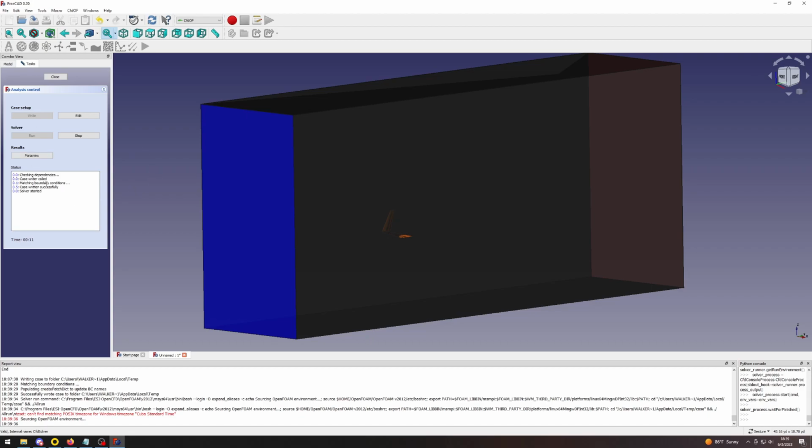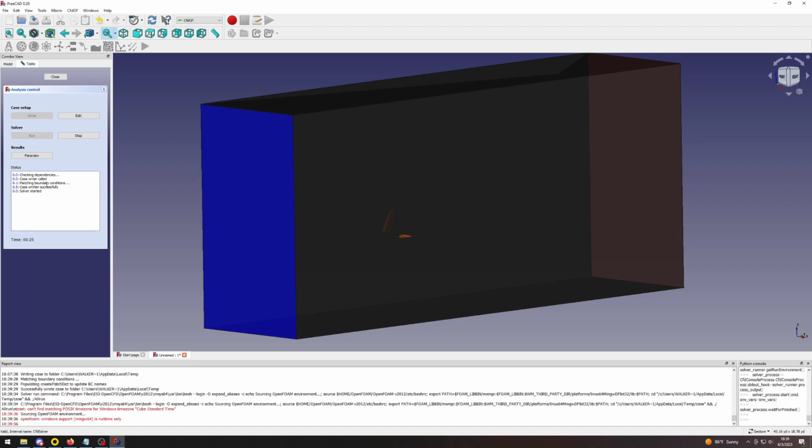And that second viewing of ParaView, where we open that program, is where we can really start calculating lift and drag as well as visualizing airflow, and there's a few different ways we can do that that are pretty cool. So I'll walk you through that when this is done. It usually takes a few hours, but what'll happen is it'll bring up a screen with residuals. Essentially, when the residuals get to a low enough value, the oscillations in the air currents have stabilized, so to speak. That's when we know the results are going to be fairly accurate, and that is when you can view them. Although, with this program, we can go straight into ParaView from any point.